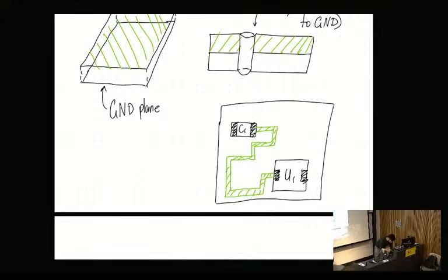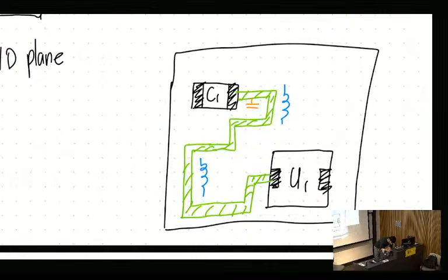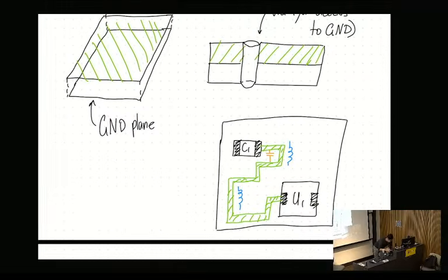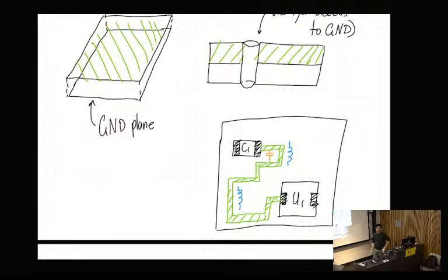Yeah, so lots of parasitics, lots of inductance along here, very bad. Another thing that is also pretty bad is there is capacitance sitting between these two layers here. Anywhere you have two pieces of metal close by, there is parasitic capacitance. And so the obvious fixes there are to make sure you have very short return paths, and you also don't try and loop around like this, because there's also the EMI problem: if there were components here, then I might have formed a board loop, which increases the amount of magnetic interference.